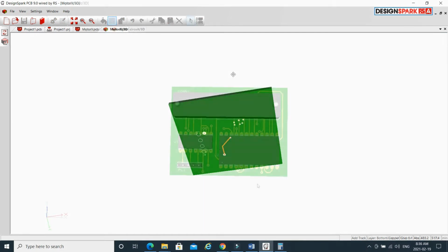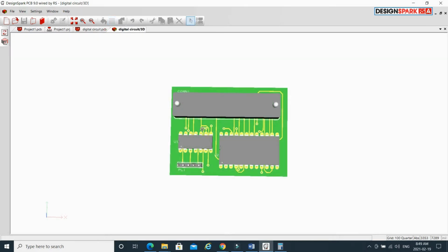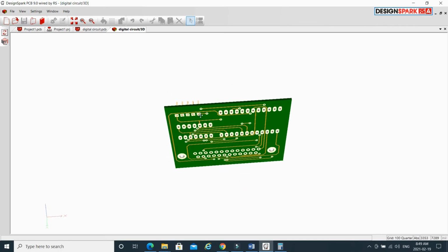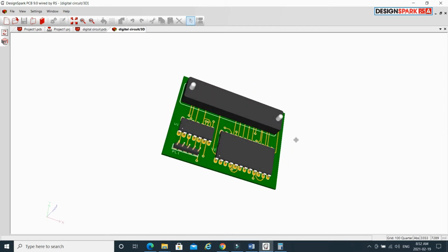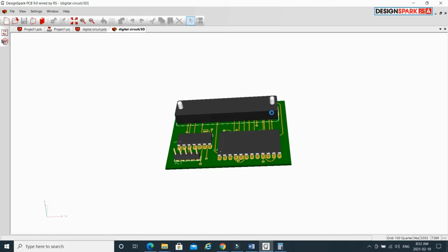A compact PCB with complex circuitry normally consists of many vias. The disadvantage of vias, however, is the additional resistance and the extra manufacturing cost to the PCB. Therefore, we will try to minimize the use of them as much as we can.